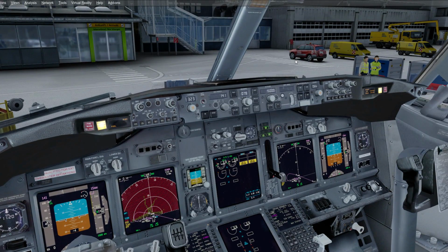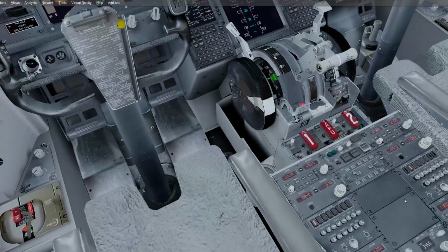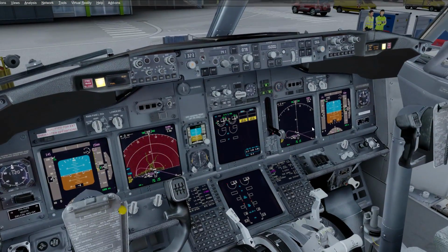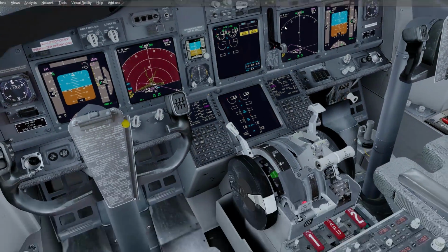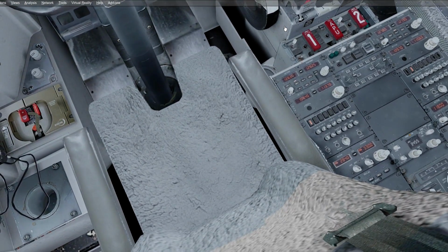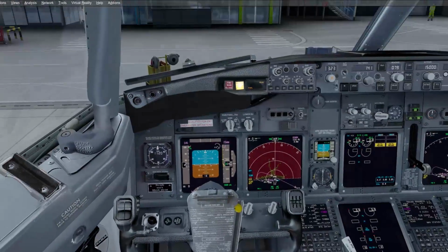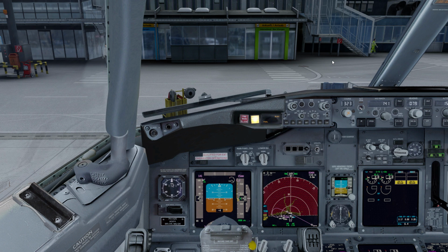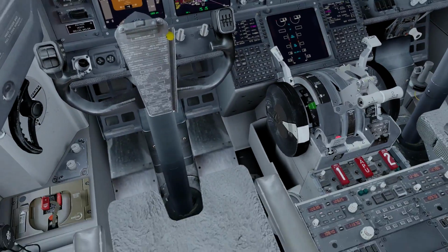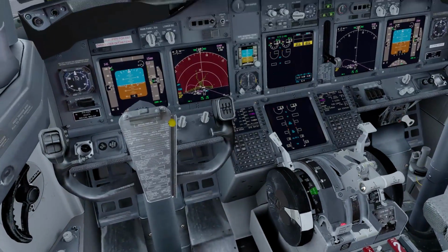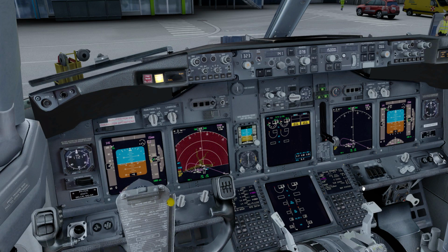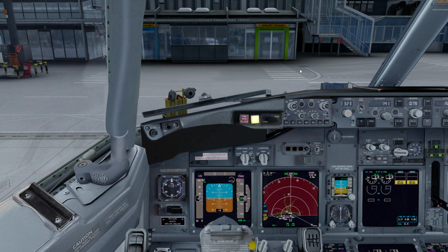So the reason why you would enter these courses and also tune these VORs or localizers is simply to get a little bit more situational awareness during the departure, and in case the FMC fails, you have the conventional navigation as a backup. Okay, so when that is done, when you're fully prepared for the departure and everything has been briefed and set up, you kind of have to set all this up to your own liking and all the frequencies according to what you need. So I can't really say that much about it.